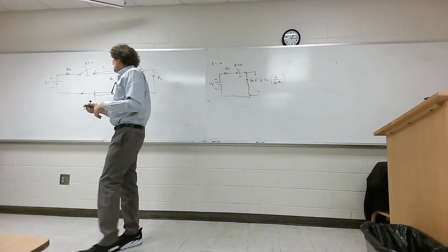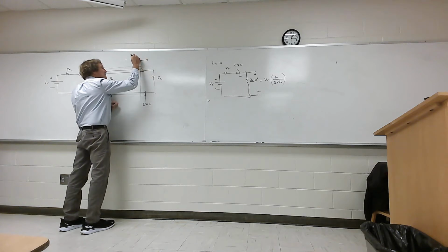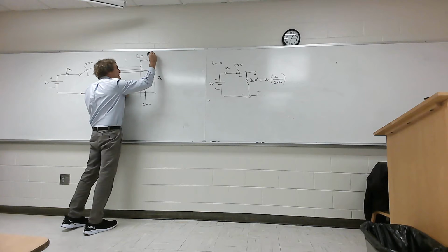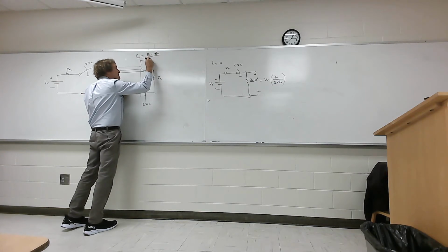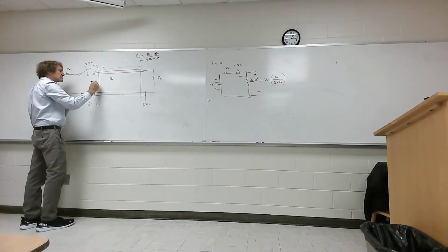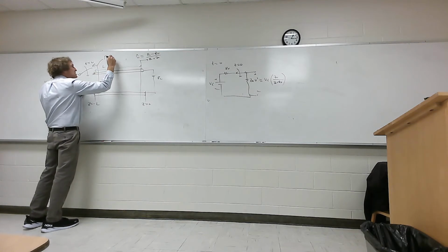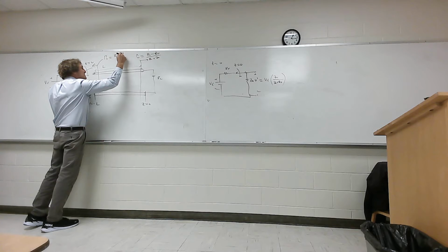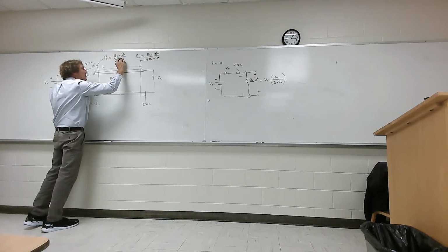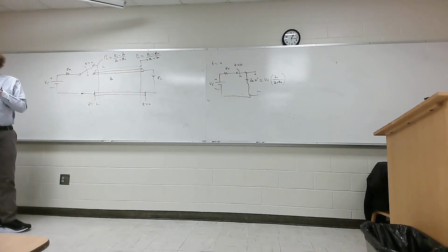Now, after that, you need a few other things. I need the reflection coefficient right here. That reflection coefficient is the impedance I'm going into, minus the impedance I came from, which is Z0, over the sum of the two. I need that reflection coefficient at the load, and I need this reflection coefficient this way. The reflection coefficient of the source is the source resistance minus Z0 over Z0 plus Rs. I need that. Now, y'all follow what I'm doing here?